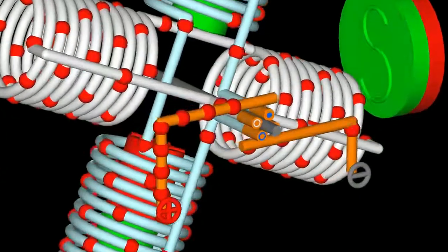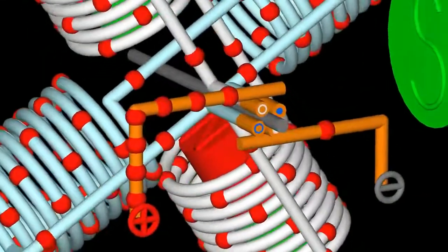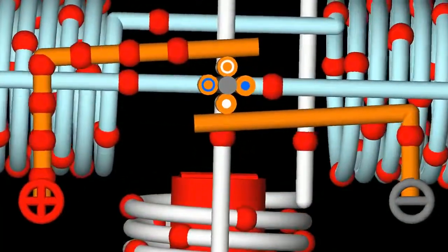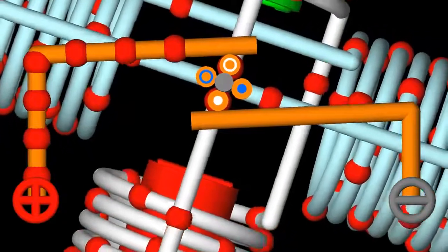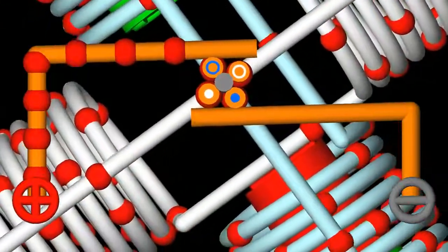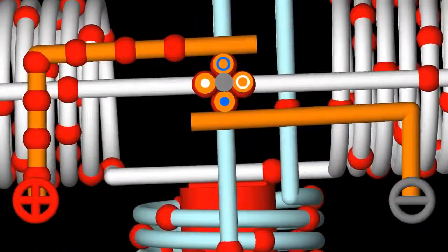A way around those problems is using another pair of coils arranged perpendicularly to the first pair. The commutator periodically energizes the white marked and the light blue marked pair of electromagnets. Furthermore, the polarity is swept each 180 degrees.